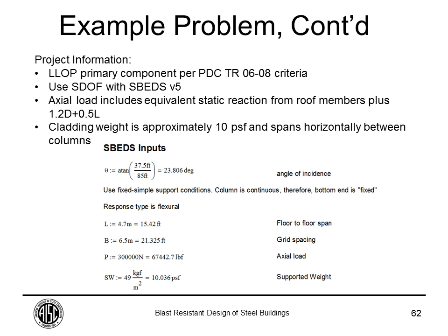Well, we do not increase the modulus of elasticity, and I don't understand the part about the conservatism. The reason that we put the dynamic increase factor is because of the strain rates. The component is responding so fast that it is effectively going to be stronger than that lower value. The other thing to keep in mind is that just because you reach what we call the yield point, with or without the DIF, it's not really a failure. At that point, you're deforming plastically, and if you design your connections right, you shouldn't have any component suddenly flying into your room, because your connections will remain attached.